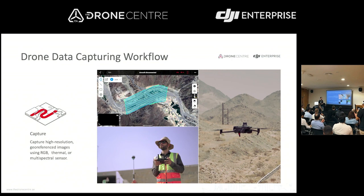This is our drone data capture workflow. This is how we plan the mission. We plan it parallel to the mountain, because we have 2 mountains here. If we make it perpendicular, maybe the drone will hit the mountain. So we plan it parallel. Also, we plan 90% overlap and side lap, because we need to determine each feature, like the trees, building, road. We need everything around the pipeline, because here we have a pipeline. Our aim of the project is to determine the pipeline and all the features around this pipeline.